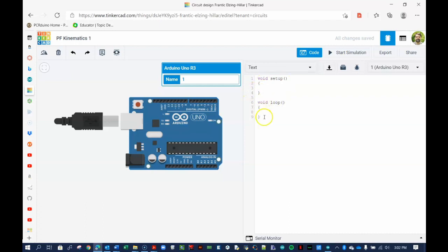So you can't get rid of those. Those have to stay. And Arduino forces you to keep both of these functions, the setup function and the loop function. You have to have those two functions in all of the Arduino programs, or what Arduino calls sketches. All these Arduino sketches have to have these two functions.